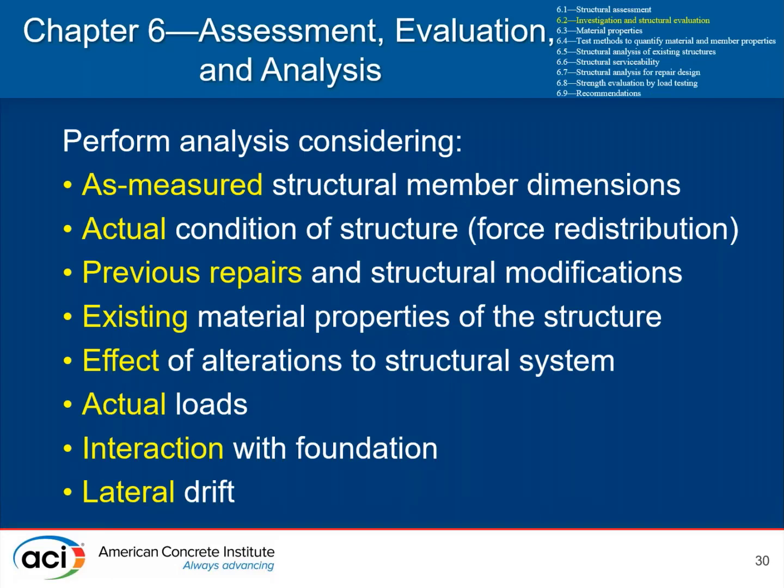So the analysis, again, is going to account for and consider the as-measured structural member dimensions. And I think, as part of the Chapter 6 discussion in Part 2 of this webinar series, it was discussed about measuring and evaluating the structural member dimensions in order to confirm what is there, particularly if no drawings are available, but even if original drawings are available, confirming those member dimensions becomes critical to ensure